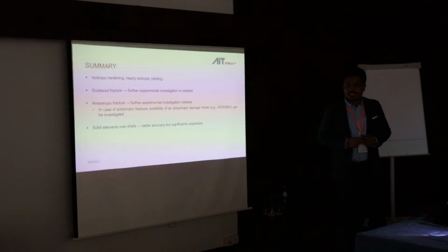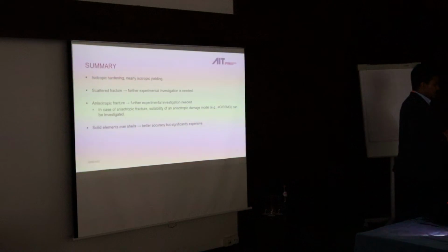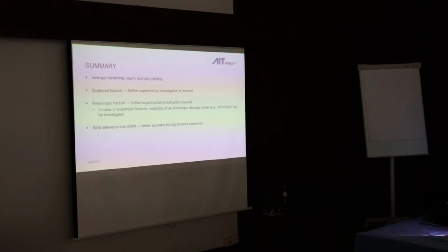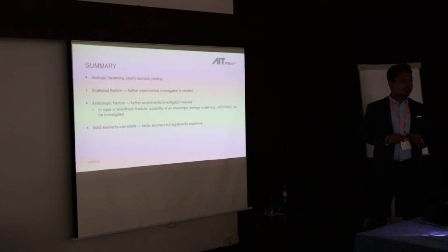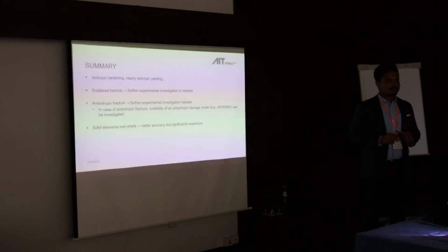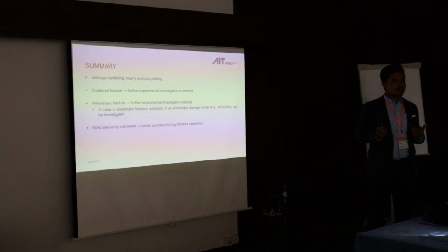I didn't write it here, but with the shell model, the simulation took roughly 15 minutes using 64 CPUs in our cluster, and with the solid it took roughly 12 hours. So you can imagine the difference in computational effort.